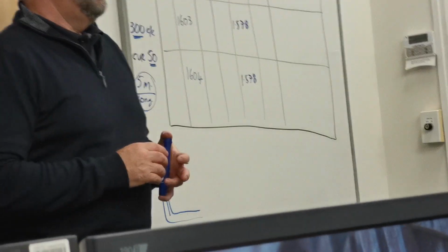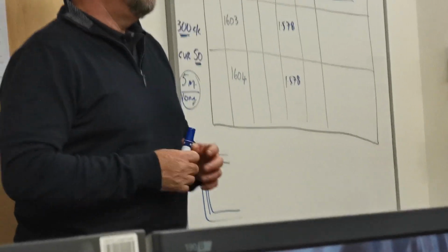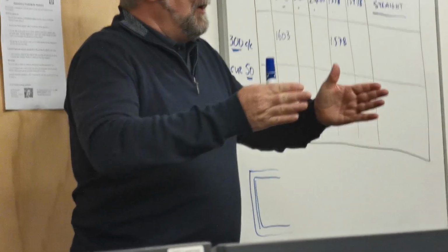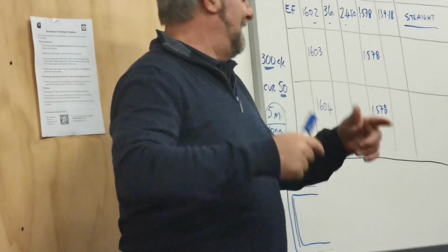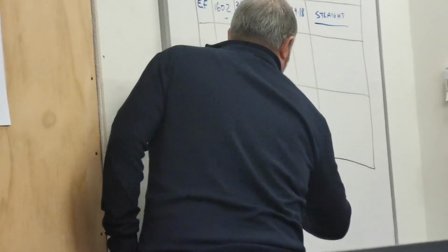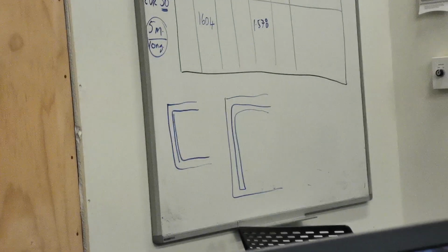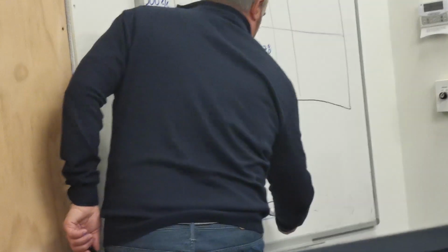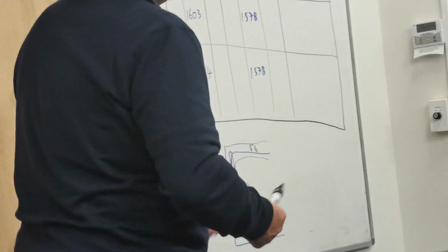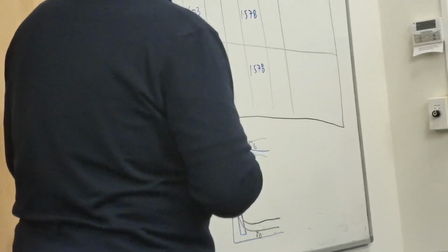With reinforcing, it's like when you're helping your grandmother do quilting, those things that fit on the bed. You always put the lines as far to the outside as possible. So the reality of that is this. The bar comes along and down, and another one in another colour goes along and up behind it or in front of it, so that we end up getting our 50 cover all the way around. Right? So now that we know that it's pushed right up against the edge like our grandmother's quilt, we can now do the calculation for that bar.